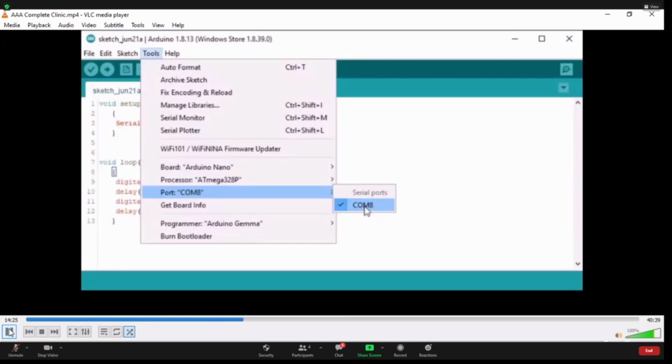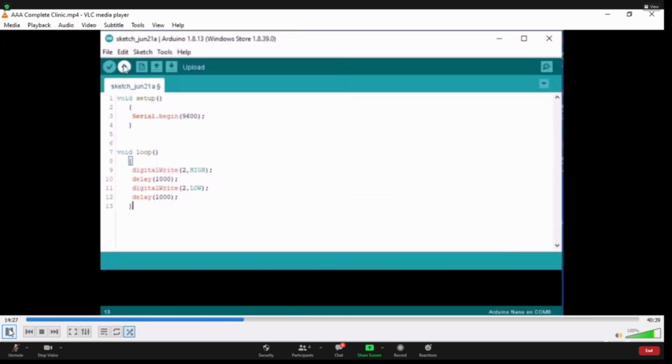In the upper left of the IDE is an icon with a dark green arrow on a teal-colored circle. This is the icon that downloads the sketch from your PC to the Arduino. So let's click on it. Down at the bottom of the IDE, it will indicate that the sketch is compiling, then uploading to the Arduino. In a few seconds, the LED will begin to blink.